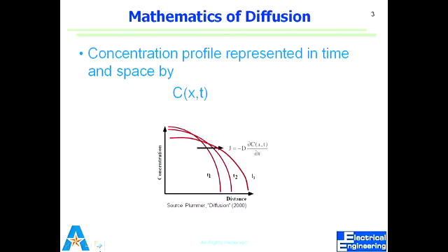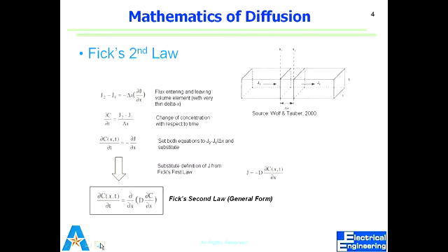So what are the two steps of diffusion? What do we do first? Pre-deposition, right? So we need to get all the dopants into the substrate, and then we drive them to the depth profile that we want. So in time and space, this is how it looks.